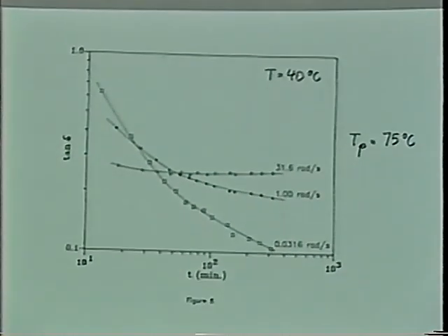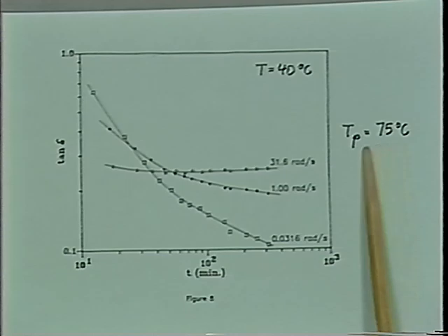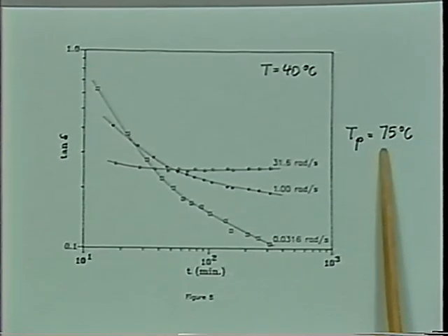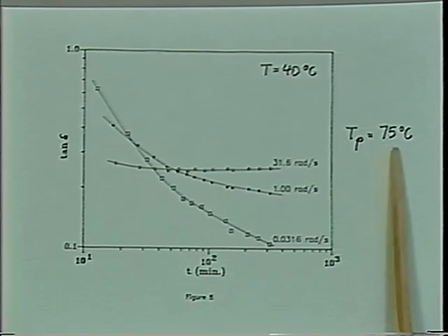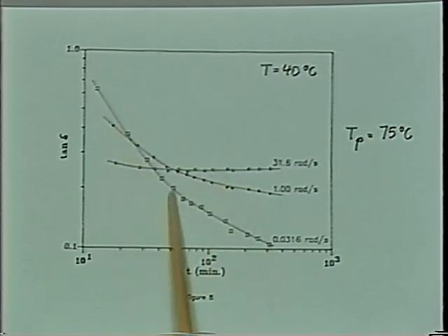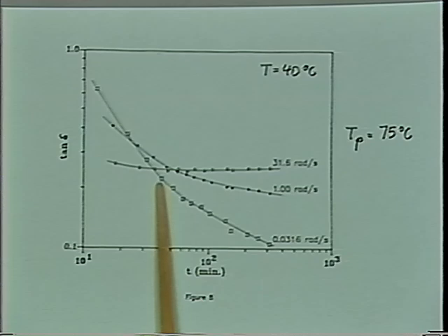So everything is fine until we take the sample which had only been heated barely above its melting temperature. The melting temperature was a melting range, but the middle of that melting range was 65, and we only go to 75 degrees. It's a liquid behavior in the beginning, but then when solidifying, somehow tan delta is not giving us one crossover. It must be a masking of two types of phenomena. It's not just gelation. There's maybe a phase separation coming in, or